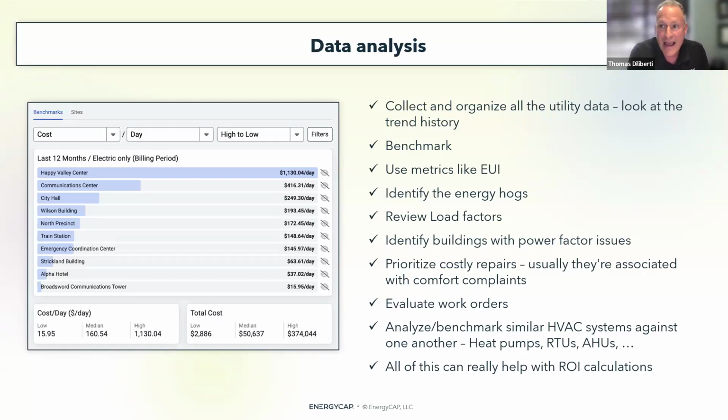If buildings have a lot of activities going on, whether they're manufacturing activities or maybe there's science research activities on a university campus, they might have systems that have to run 24/7 and thereby consume a lot of energy. So just looking at EUI or looking at benchmarking metrics does not tell the whole story. You have to look beyond that. You have to understand truly how the building is being utilized so you can do some fair comparisons.